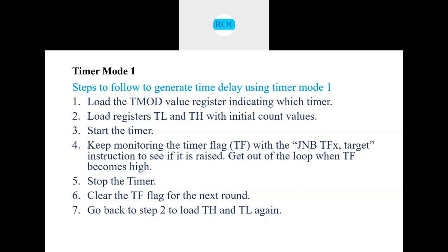When you start it, what will happen? The timer will be receiving the clock signals. As it receives the clock signals, it will keep on incrementing the count in the register, and whenever it reaches the maximum value, it resets, and it will set the overflow flag to 1.